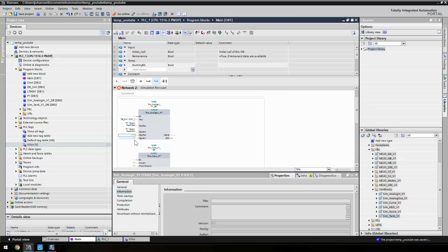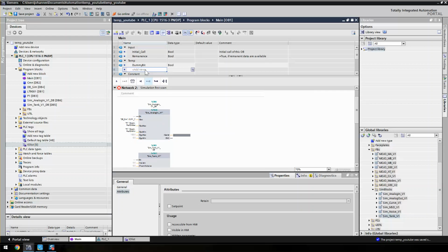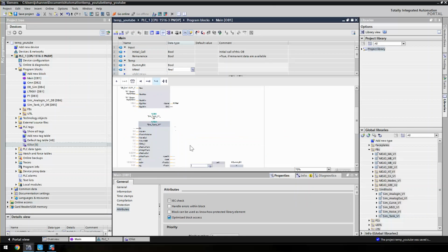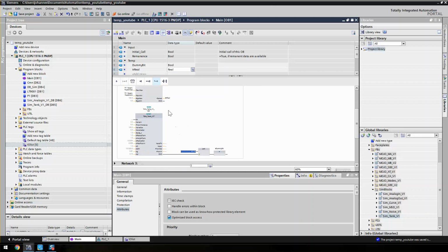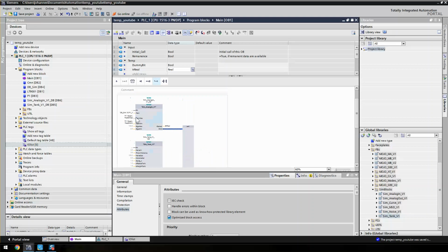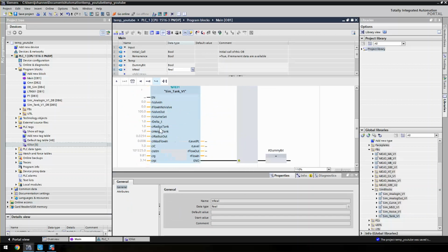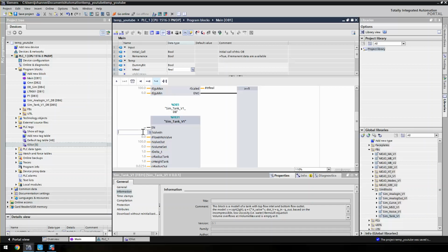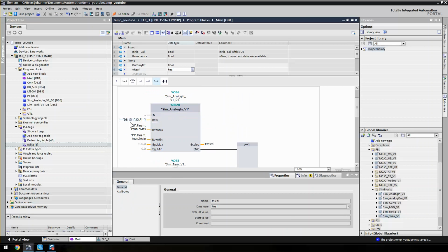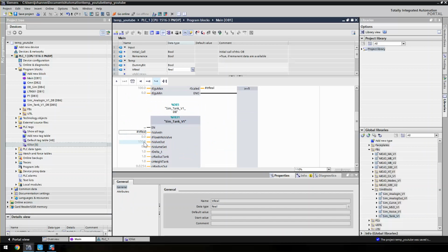So now we're converting it from 0 to 100%, and then we need to dump the scale value somewhere. There we go. This OR gate here doesn't do anything, it just allows me to cram all of this into a network. So first we convert this analog value 0 to 12,000 to 0 to 100%, dump it in here.